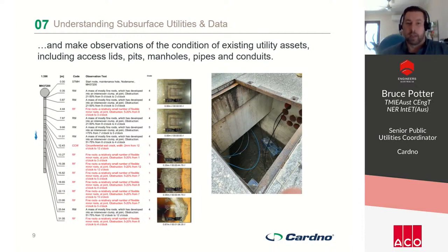On the right is where generally a utility locator would come along, who would use radio detection and GPR. When they're using radio detection, by default, they have to clamp onto an existing cable that's in the pit itself, or use trace rods to conduct a presence of a cable in there. And by default, they're able to actually open up the pit lid and look inside to see what the configuration of the conduits are, what condition the conduits are at the pit itself, and generally what the condition of the pit overall looks like. So is the existing pit structurally deformed? They would take note of all that information as well.